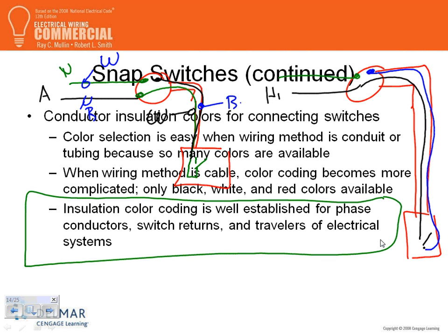You might ask, Brad, why are we re-identifying these when we're dealing with cables? Keep in mind, guys, you can wire a whole commercial building with MC and AC cable. It doesn't have to be raceway. You can wire the whole Dunwoody here with MC, AC cable without a whole lot of conduit. So why would you have to run the white wire to power it? Because the cable has two colors, black and white, and ground. Both hot.